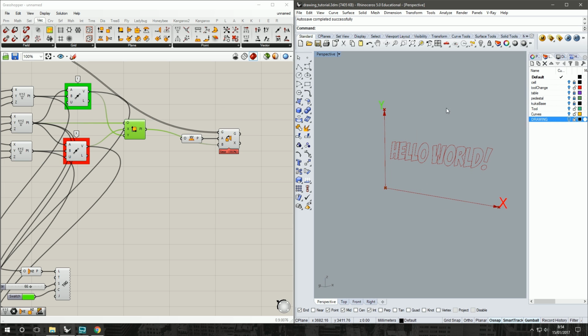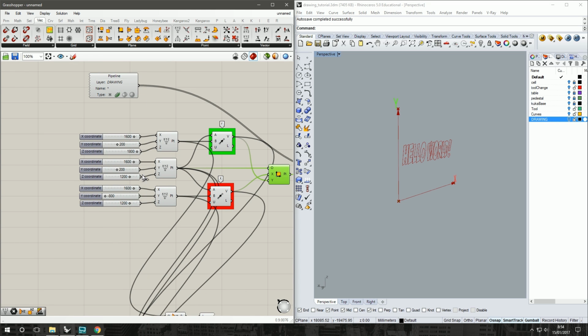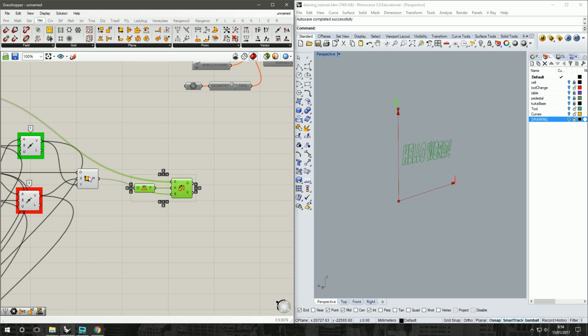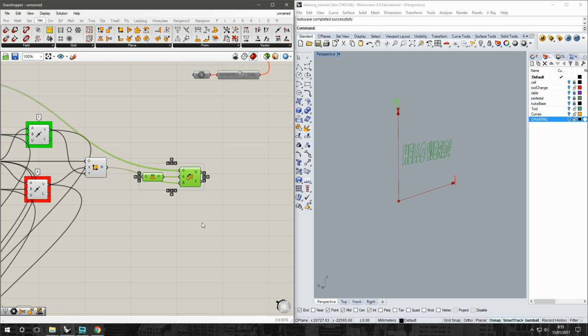Now say you're with your robot and your canvas is on a lean, or you're doing it on a surface that's not quite parallel, then of course everything updates. So you just get your actual point when you measure with your KUKA Robot, get your corners from the robot, and just put in where your canvas actually exists in the real world, and everything updates. Just in case people are coming into your cell and moving your stuff around, it's quick and easy, and you don't have to rewrite all your script. You just got to change 1 or 2 sliders and everything updates without having to worry about it.